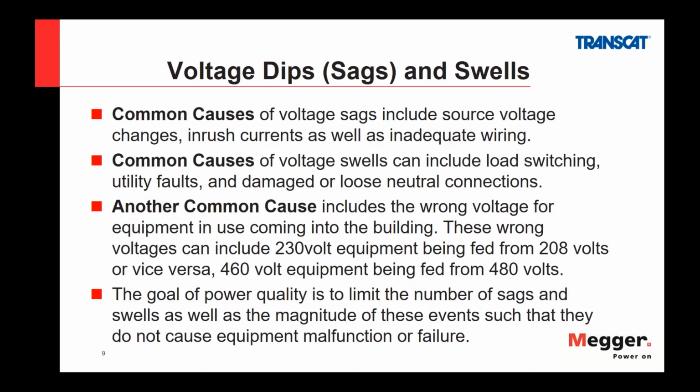Common causes of voltage sags would include voltage change, like when you turn on a motor and rush currents, as well as inadequate wiring. Voltage swells would include load switching, utility faults, or even neutral connections being damaged or loose.